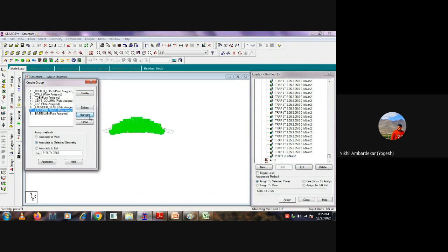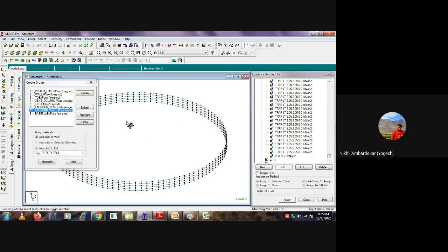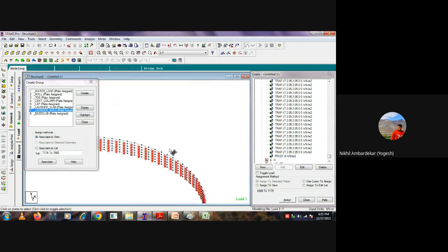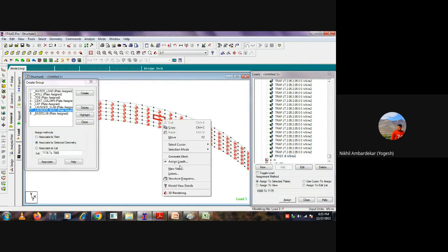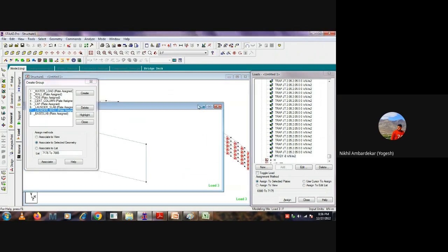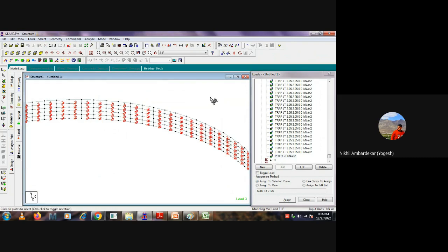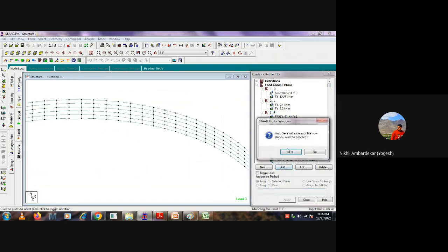Next, I want to add triangular load on the Launder wall. So for that, I just keep open this Launder wall. I want to see its orientation, local axis. It should be same as the previous one, but I just want to make sure. New view, I can create this view. Same, Z is outside. Add, save.